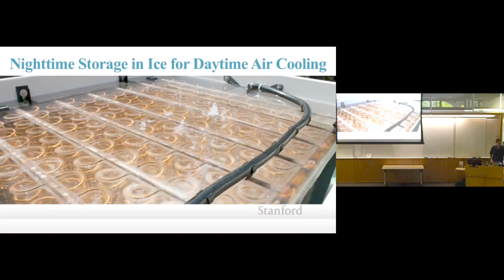Quick question about ice storage, because water has this property to expand when cooled below 4 degrees Celsius. Would the constant expansion and contraction have any adverse effect on the, I presume, copper heat exchangers? Well, I would assume this is open on the top, so the expansion would occur. It's not constrained. It's not like in a box. If it were in a box where it couldn't expand, then you would have that problem. You'd probably squish the pipes. But it's free to expand upward in that case.